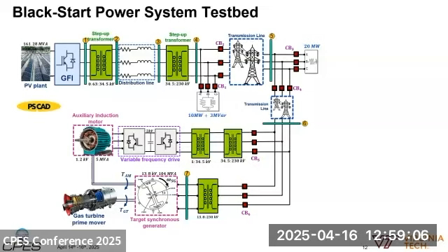And we know that under a total blackout, a gas generator needs to be started from a standstill state, with the Black Start network side providing the jumpstart power. This cranking process should be realized by a variable frequency converter driving an auxiliary motor. In the meantime, the synchronous generator is accelerated by the auxiliary motor rotating the attached shaft between them. And also, there is mechanical torque coming from a gas turbine prime mover to drive the synchronous generator.